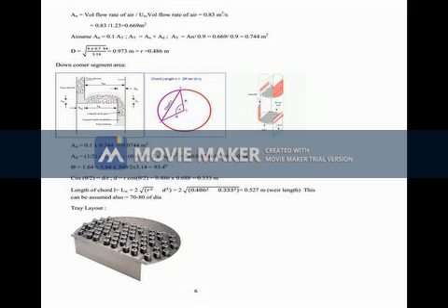Then to find out, 98% is to be removed. So for that you require mole ratio, that is capital Yn plus 1 is equal to small yn plus 1 divided by 1 minus yn plus 1, 0.06 by 0.94, 0.064. Then Y1, the amount of acetone in the outlet stream, is 2% of Yn plus 1, since 98% of acetone is to be removed.